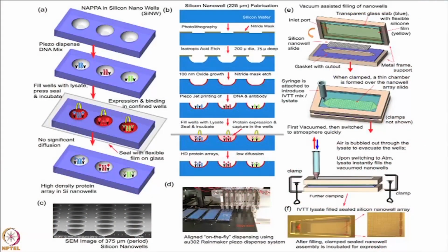So we've been thinking about ways to get around that. And this is the method that we've developed. What we do is we take silicon, the same material that you use to make computer chips, and we use the same technical approach that they use, what's called photolithography, whereby shining light on the surface you create a mask, and then you etch it with chemical compounds that etch away the surface, and you essentially can wear away the surface of the silicon.